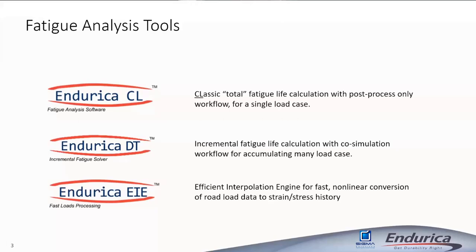Endurica DT is our incremental solver. The incremental solver allows you to compose sequences of many different load cases, right? So on day 1, maybe you have a certain load case, and on day 2, another load case, day 3, another load case. With Endurica DT, you can compile as many different load cases as you want. You can calculate residual life or residual strength if you prefer. Endurica DT allows you to use a co-simulation mode.